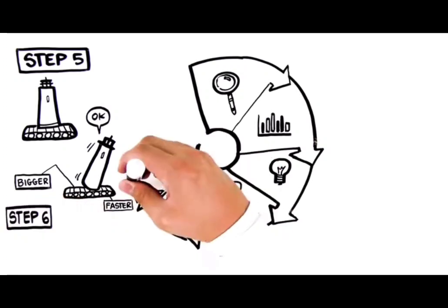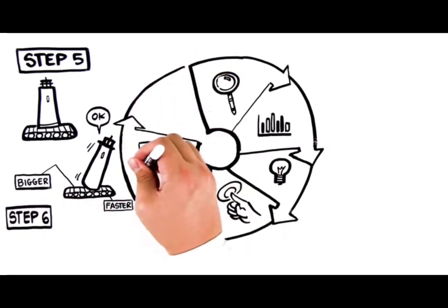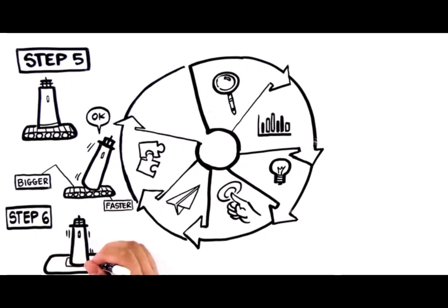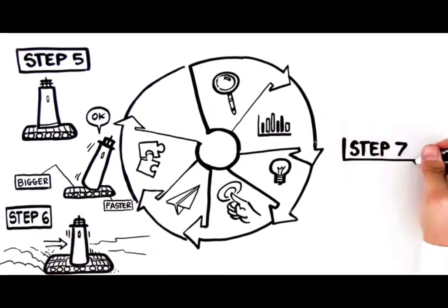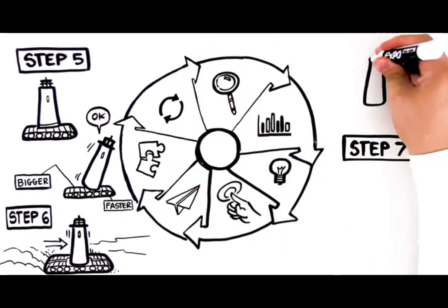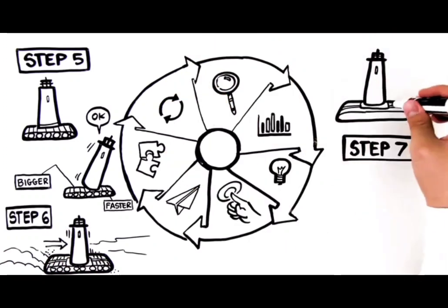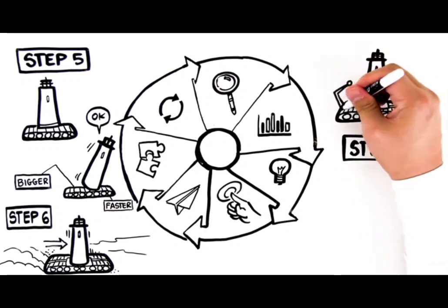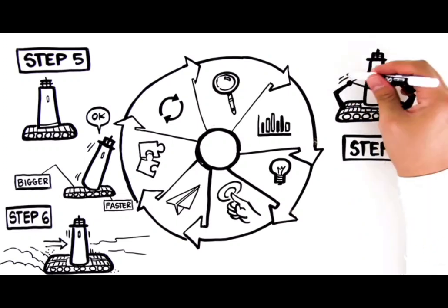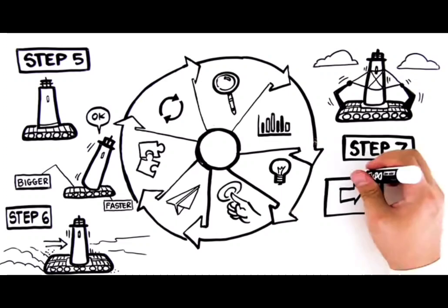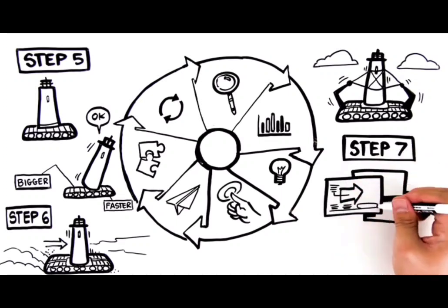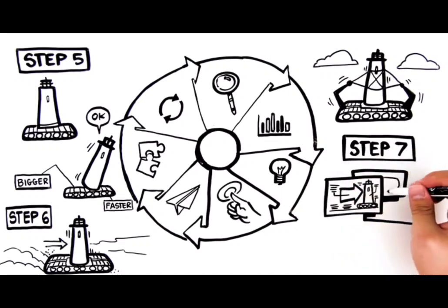Step 6. Test and evaluate the solution. Test your prototype, collect and analyze data, and document your design strengths and weaknesses. Step 7. Redesign. Based on the results of your testing, make improvements and identify the changes you're making. The design process involves multiple iterations and redesigns. You'll likely test your solution, find new problems, make changes, and test new solutions before settling on a final design.